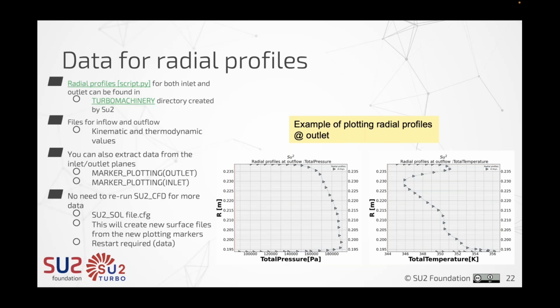The only big difference is that they went with k-epsilon, which is easier. With SST, at least with the 2003 version, it's more encouraging, but with the 1994 version my values are totally off.